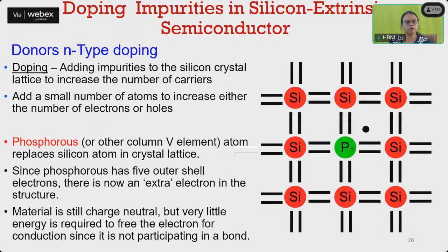So we have got two types of doping. First, let us check the N-type doping. We have seen the silicon lattice. Now we have removed one silicon atom and put in one phosphorus. Phosphorus has 5 electrons in its outer shell. So 4 are bonded with the 4 silicons surrounding it, but 1 electron remains to migrate.